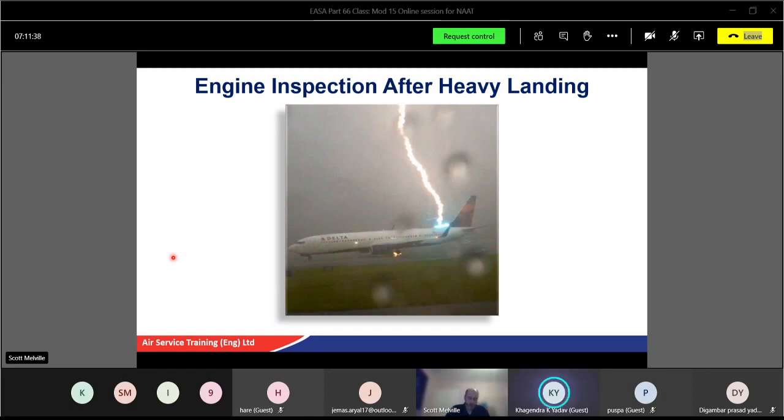It's computed by the FADEC, right? Yes. You can tweak that. We did something with the Tornado aircraft with the DECU, same as a FADEC, but called the DECU. And we actually changed the flat rating of the engine. What was called derating. So we lowered that shape, the ceiling, the flat part, the flat rating, a little bit to allow the engine to survive a bit longer, because all these jets we used to work on are now out of service.